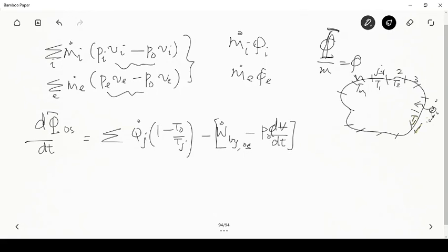So this is the exergy change accompanying work transfer, minus T naught into sigma dot, which is the exergy destruction accompanying irreversibility. In addition, you would have a plus m dot i multiplied by psi i minus m dot e multiplied by psi e, which is basically derived from the phi i, phi e and the flow exergy components.